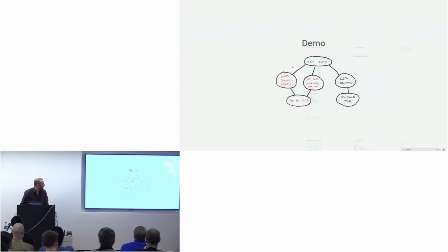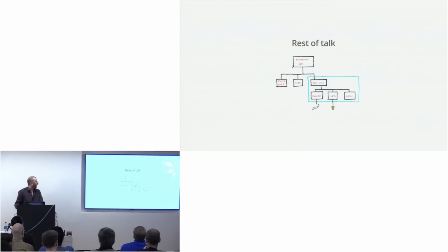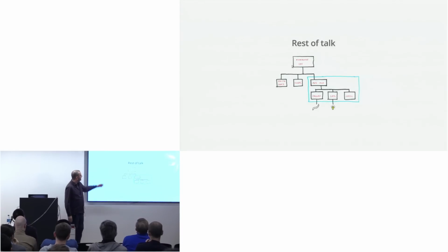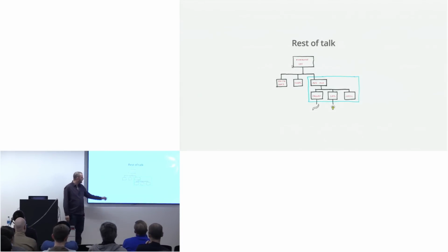So I'm going to explain how I managed to do that. What happened, when I pressed that button, I basically reset the FPGA, which caused it to load the FPGA image, and that has in it this vendor CPU, the Microblaze, that's attached to 256 meg of DDR3 memory. There's a little timer core in there which generates interrupts up to the CPU.